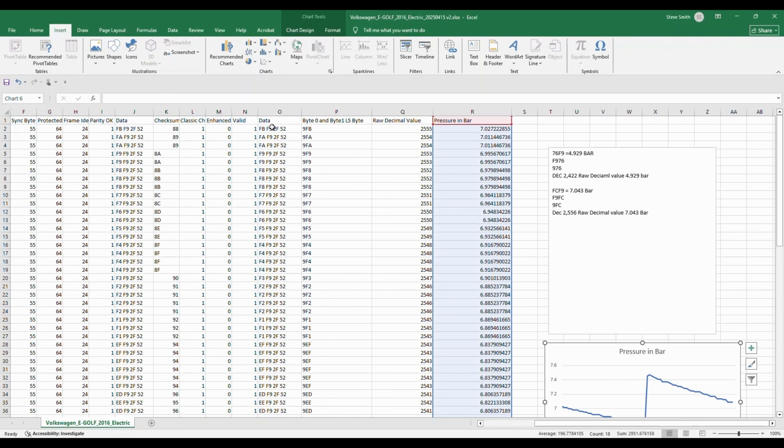We need to change them to least significant byte first, so little endian, and that is simply converting FBF9 to F9FB. We know that the second F of byte 1, because this is byte 0, this is byte 1, never changed, so we dropped that to 9FB. That gave us our 12 bits of interest.